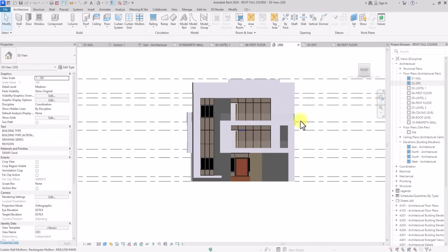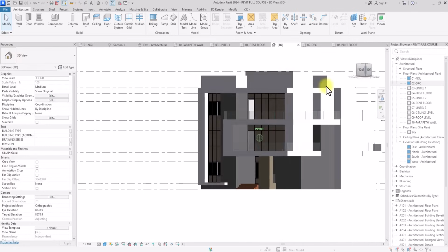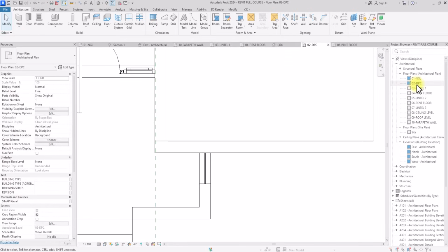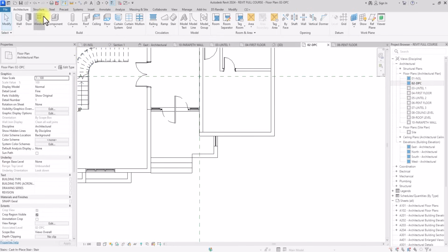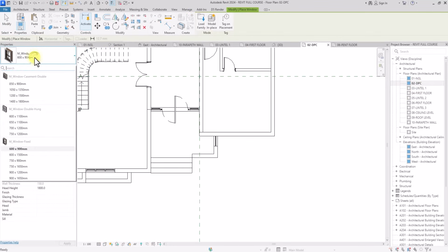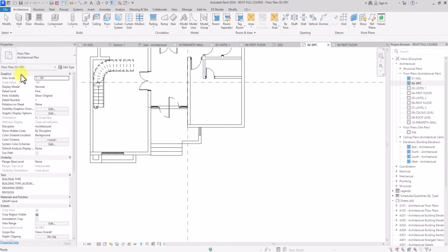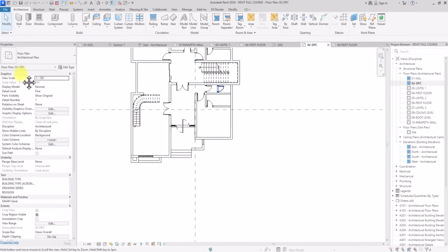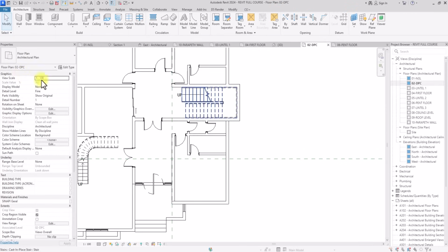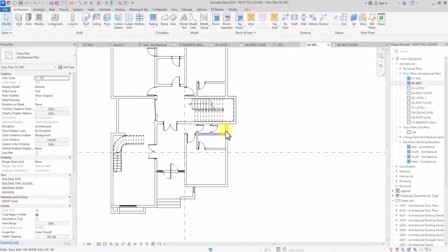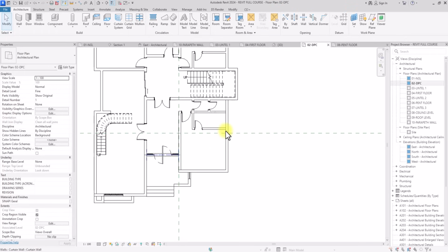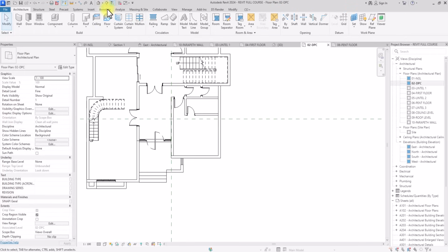Okay, so now I'm going to be working more on the other fenestrations. Typically you could go to DPC, go to Windows and use Revit windows, or you could import windows, but I don't actually use windows while modeling because I prefer using cutting walls as windows because of their versatility. I've also made a video on how to use it, so you could check that out, and in this video I'm still going to share some tips I use with this method of modeling.